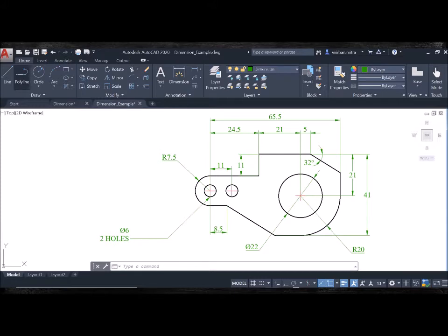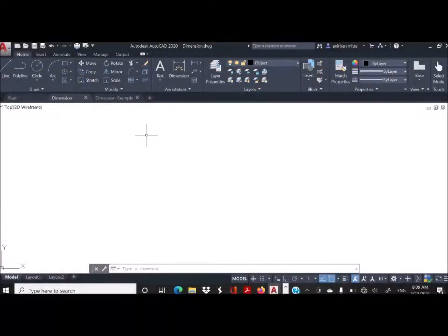In fact, for consistency, dimensions in engineering drawings are generally governed through certain rules and regulations. The focus in this video is to learn how to do dimensioning in AutoCAD. So let's move forward to that. However, before one begins to dimension a AutoCAD drawing, it is essential to create a dimension layer. And from the point of view of effective organization of drawings, it is always a good practice to provide all the dimensions in this particular layer, that is the dimension layer.